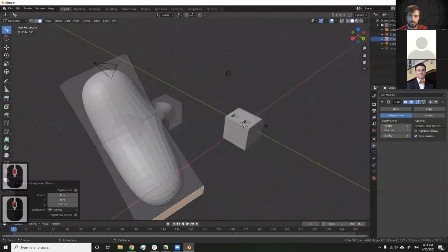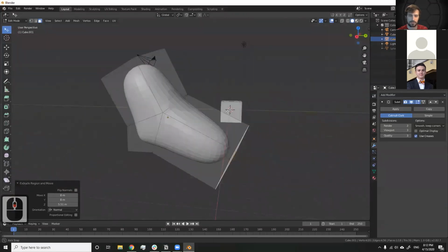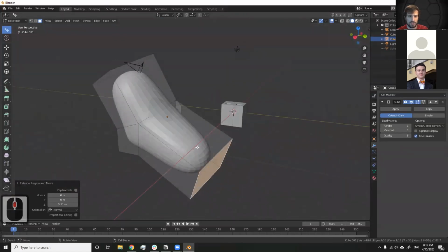So you have two different options for it. You can leave it where you have this kind of ghostly see-through look where you have the cube on the outside and you can see the smooth modifier one on the inside, or you can go over into your modifier tab on the side and click this final option, this triangle one, and what that will do is it will suck these vertices that you're editing down onto that surface like this.